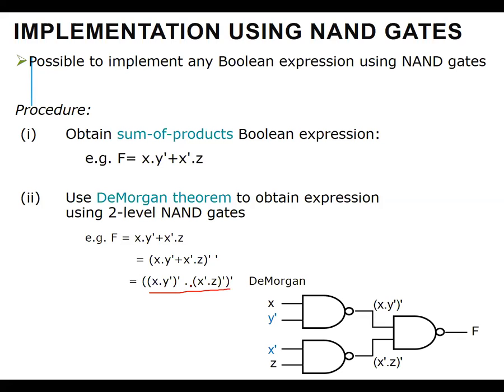So you have products here. Here a product, here again a product, and here again a product, and the complement of these two products and the whole product. Okay, so that's why you can represent these two terms using NAND gates only. Okay, so when you represent in NAND gates, it should be an AND and the complement of the AND. Should be a complement of AND in and should be a complement of AND in. So do you get what I say? So these are important.